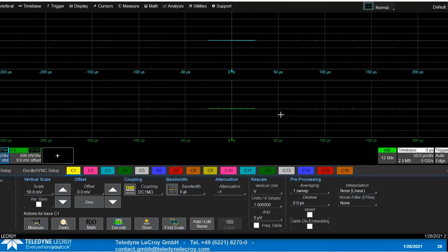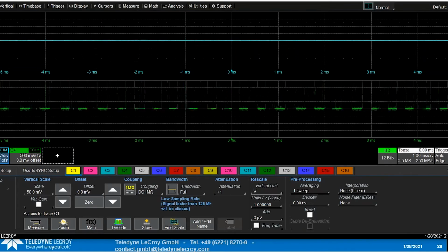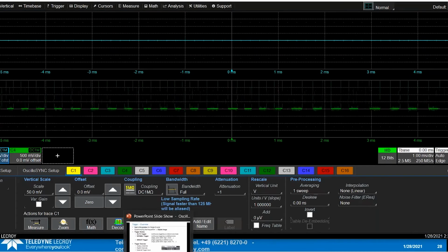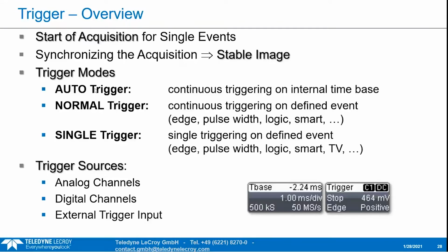To make my point, oscilloscopes have these things called auto, normal, and single shot triggering. The scope's trigger circuit is called different things on different scopes too. There's run and stop, and if you're in run, there's a setup for you to choose whether you want auto or normal.